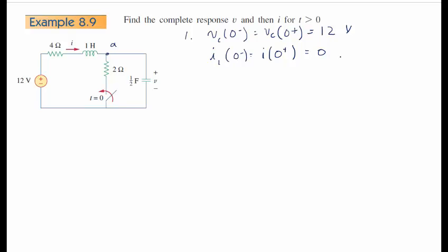The next thing you have to do is find the derivative, at least one of the derivatives. Whether we do a current or voltage equation, we're not quite sure yet, but we have to find some derivative initial conditions. By practicing, I can see that we could get dV/dt at time 0 plus from the equation C dV/dt equals I sub C. And at time 0 plus, what happens?